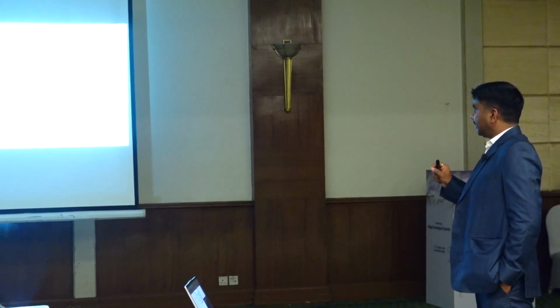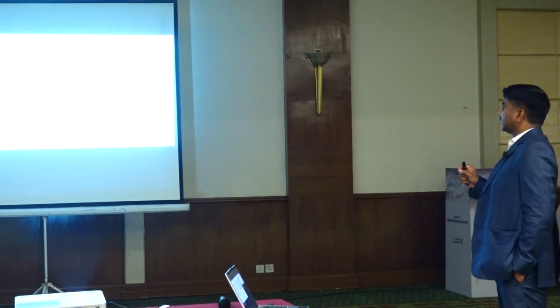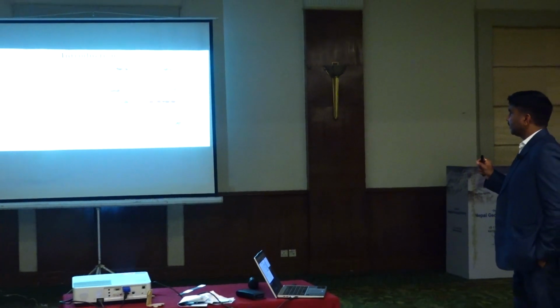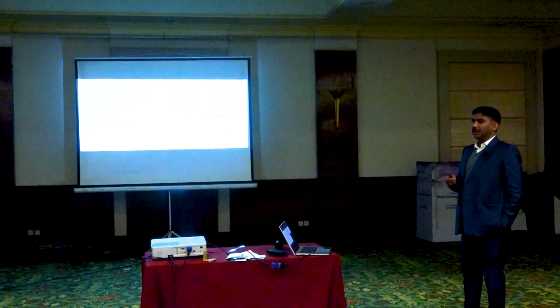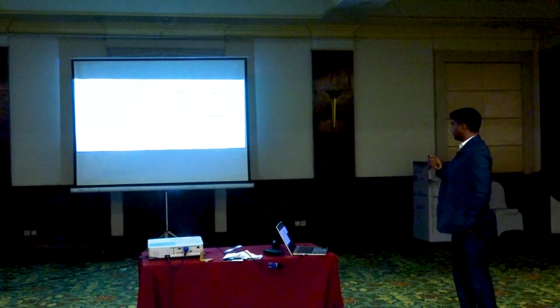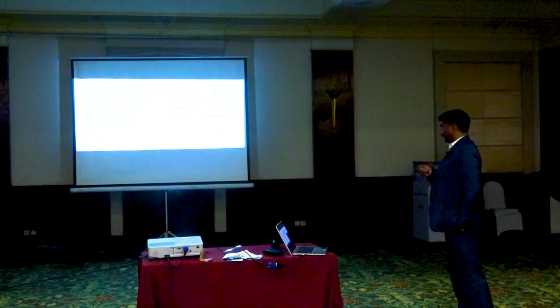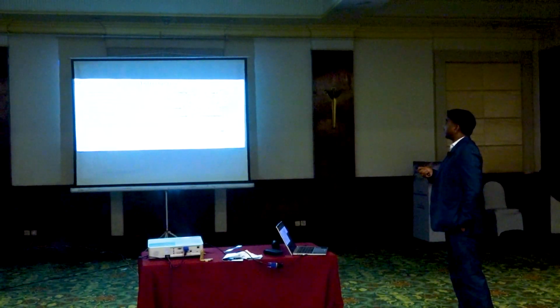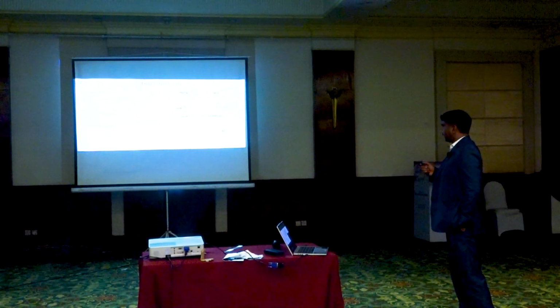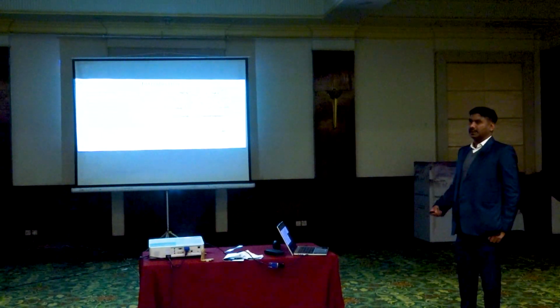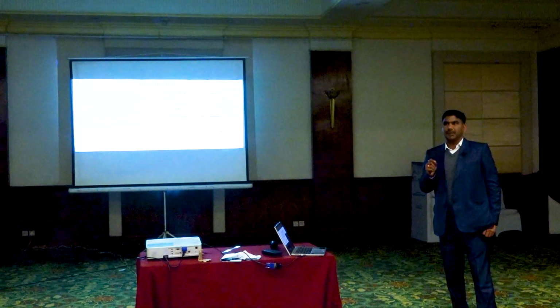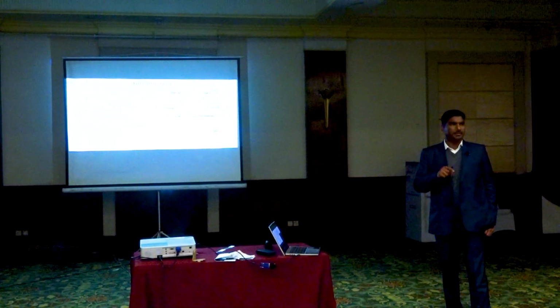Among all negative effects, the major concern is ground vibration, to the surrounding structures and habitats, which are living around where the working is going on. So ground vibration mainly depends on rock mass properties and blasting parameters. So we cannot change the rock mass properties. So we can only play with blasting parameters.